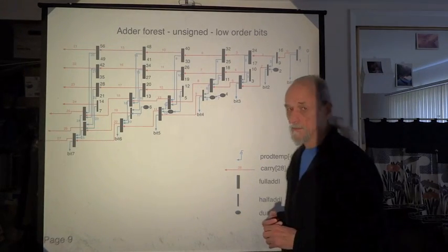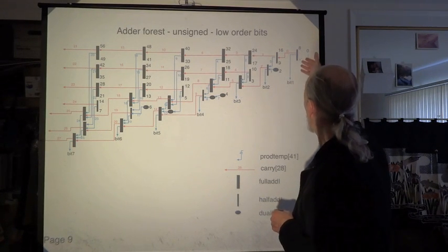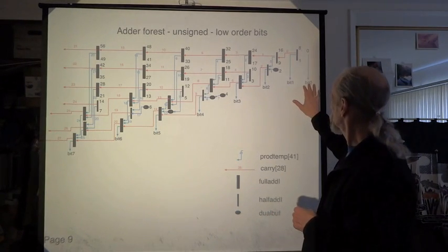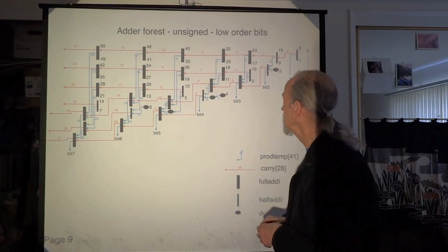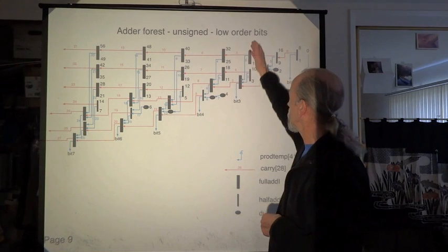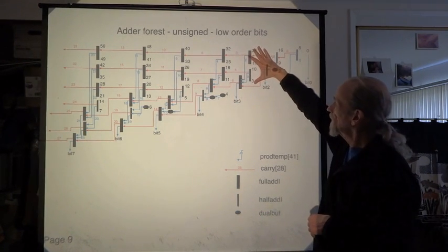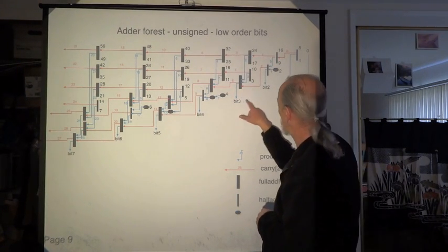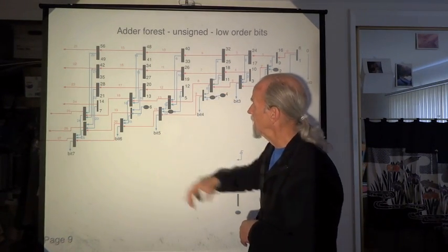So now let's look at a detail of the adders. So these are the adders, the successive adder trees for each bit. This is product bit 0, product bit 1, product bit 2, product bit 3, and so forth. And this is the adder tree, growing out of these partial products, which happen simultaneously, these which happen simultaneously. And these are the product bits coming out of the top of the adder tree, the top of each adder tree.